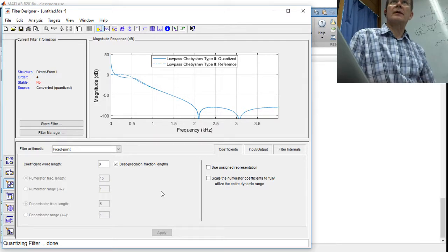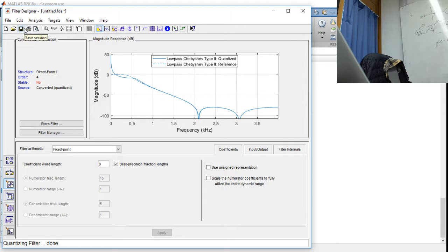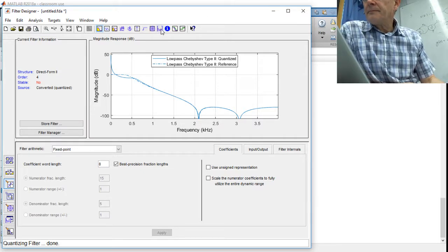Yeah, okay, there we go. So remember the 8-bit presentation was pretty good on the previous second-order sections, but if we go to a single section, meaning a 4th degree single section, we are getting lots of error already on the quantized filter coefficients. And where that comes from, I will show you.